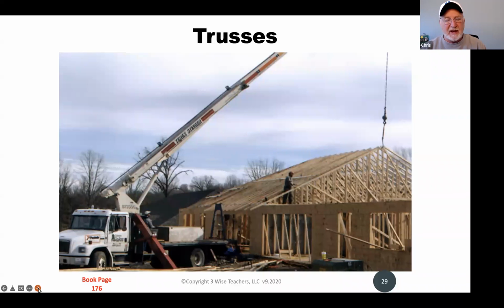Here's an interesting thing, and actually a testable thing to know about trusses. Because they are engineered structures, they allow you to have houses that are kind of free flowing. What I mean by that is you don't have to have load bearing interior walls if you have trusses, because they bear the weight of the roofing structure. You don't need a load bearing wall to hold up the roofing structure. So trusses allow for interesting interior designs because you don't have to allow for load bearing walls.